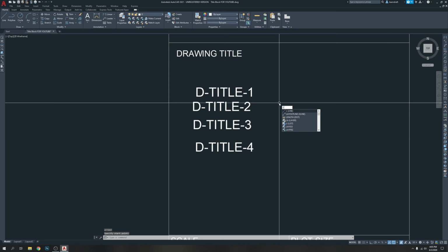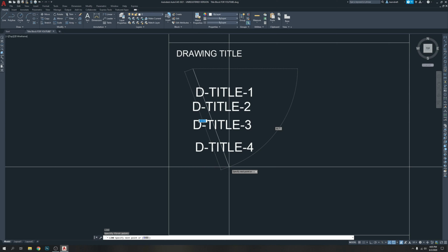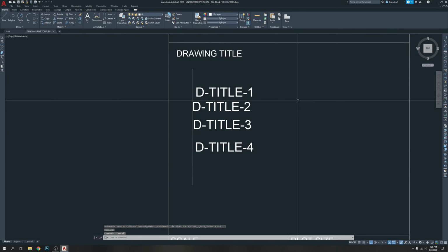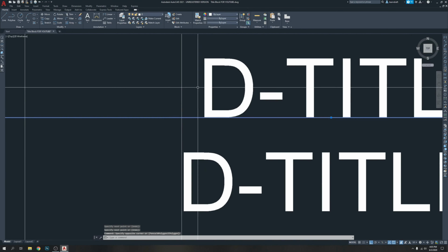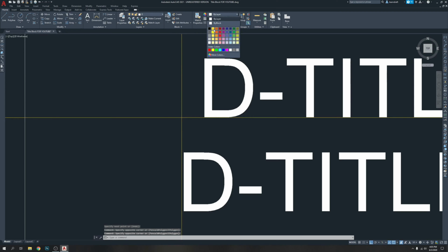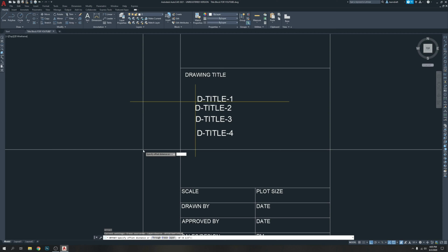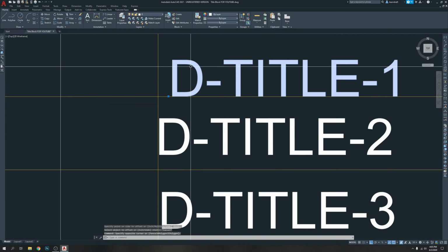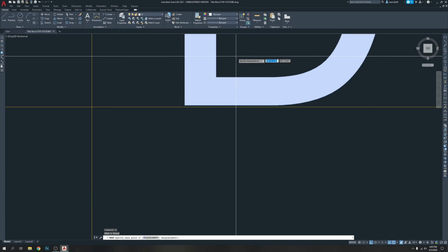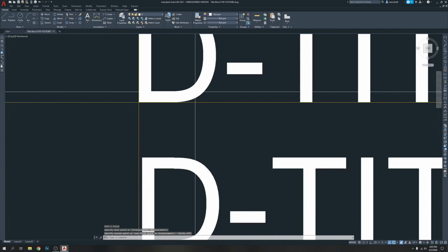So I'm going to create a line, F8, and draw a line here. Click them both, make them color yellow, and then offset, enter, 0.375, enter. Click 1, 2, 3. Select this one, click from here, press F8 so you can move it freely.